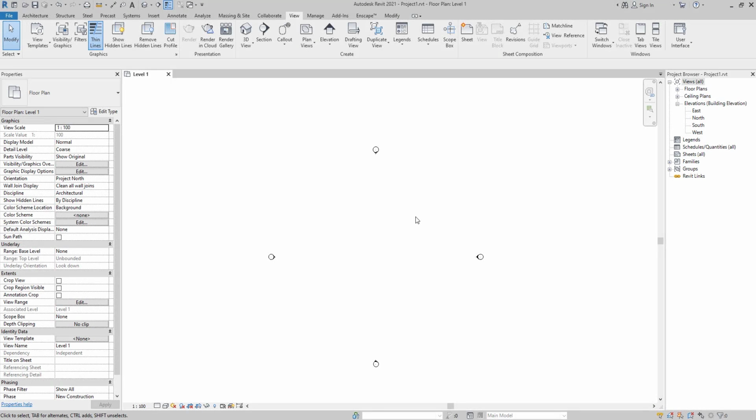In this video, we are going to talk about level, how to draft level in our Autodesk Revit program. For drafting level, we need to go to one of the views such as elevation or section, or any types of this kind of view. For example, even if you are going to have a ref plane, you can go to that option. But right now, the first option available for us is elevation.